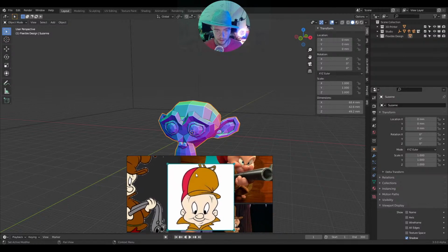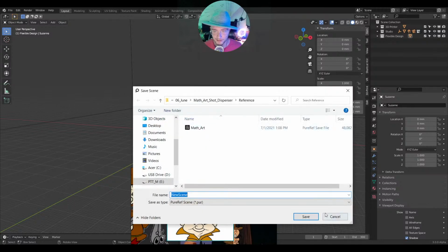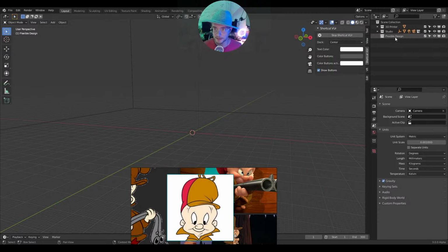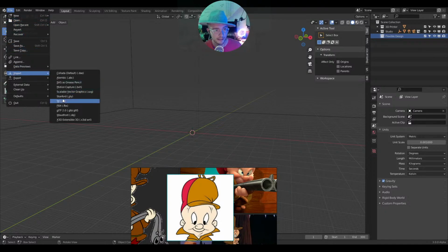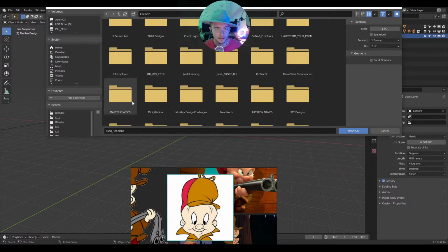And we'll just move that around as we need it. So I'm going to kind of cheat a little bit because I already have a hat that fits my head that I 3D printed a long time ago. So we're just going to use that as a reference. So we're going to delete the Suzanne and bring in my old school hat for size reference. So we're going to import an STL and let's do 2020